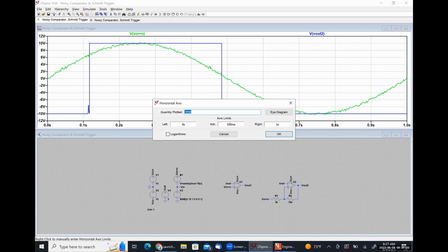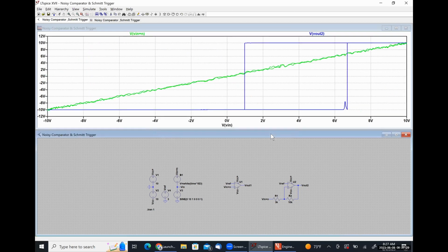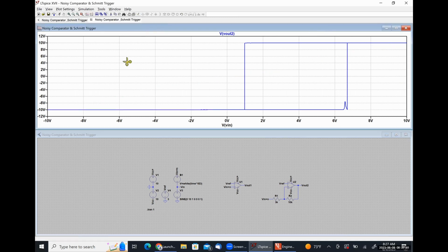So I'm going to look at V at Vn as a signal I'm plotting against. And I get this funny looking curve here. This is what would commonly be called a hysteresis curve. It actually, in some ways, shows that this circuit has, if we were dealing with a magnetic circuit, we would call it memory, but because this isn't a magnetic circuit, I'm going to call this latching, okay?